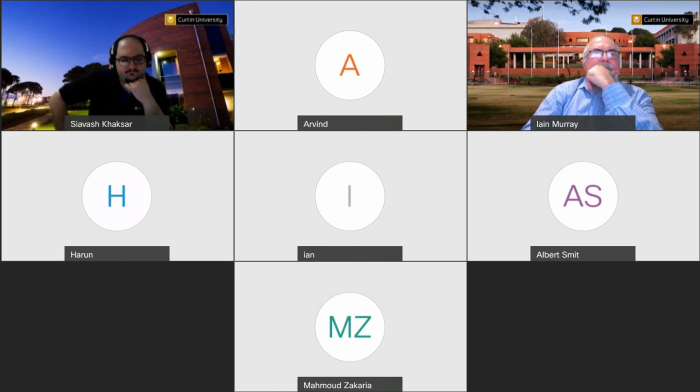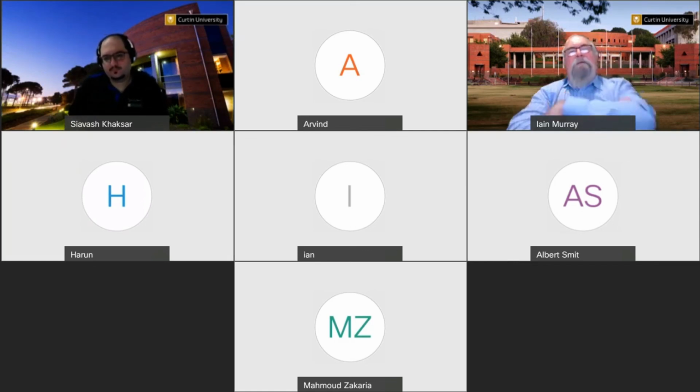But yeah, for now the best way is using an FSR on the fingertip itself, and some inductive sensor to recognize the clip itself. And the third one would be the microphone, normally, for me. And you're really looking to see if the clip's in correctly, so a vision system's probably out of the question and probably too pricey as well.